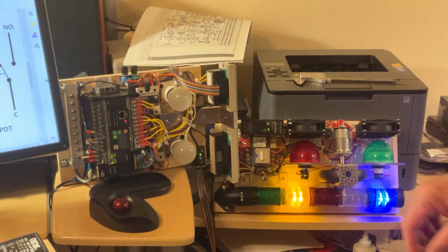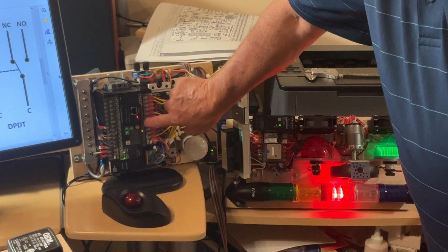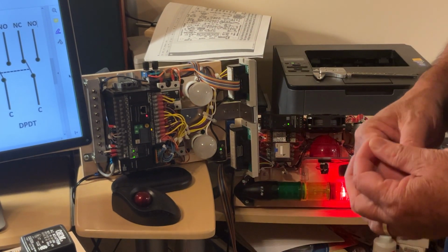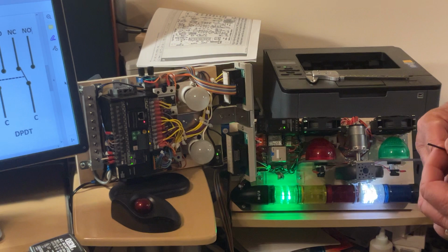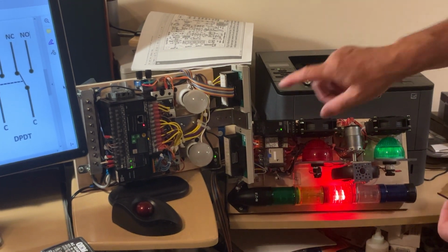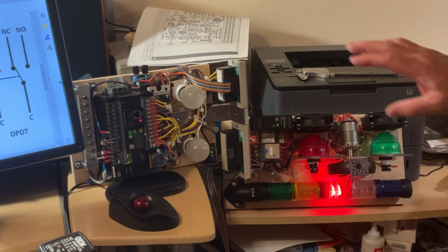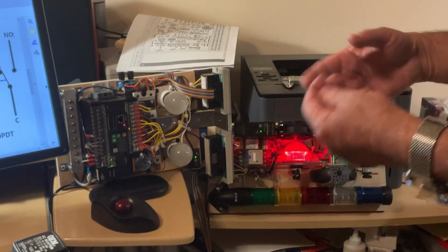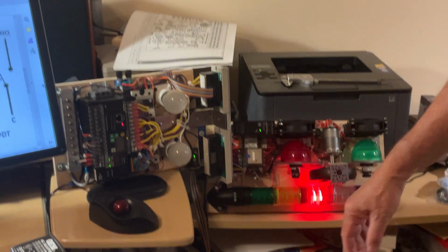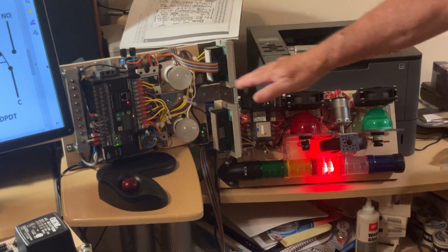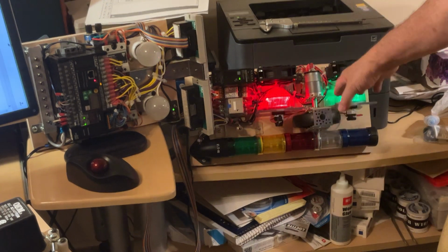Okay? And the thing is, all the LEDs monitoring the outputs, that's one of the standard features of the PLCs because each output, each input is monitored by one LED. But all the LEDs are having the same color, so it's not very easy to quickly identify who does what. Okay? For that reason, I picked up a flat cable, so I transferred the signals from the PLC in what I call an output trainer.